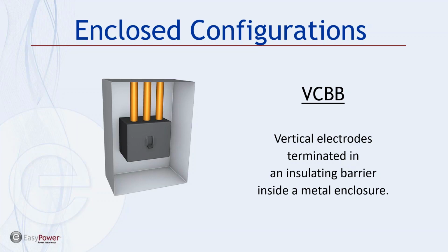And one example of that type of termination is a typical molded case circuit breaker, where we have the main feeder coming into the top of the system, and if an arc were to happen at that point, the arc would be basically spreading out or bouncing off of that barrier itself, the insulating barrier. So we'll see, the surprise was at how much higher this particular radiation was compared to the vertical termination that was being used as the default.